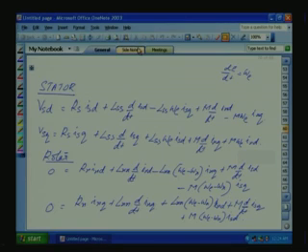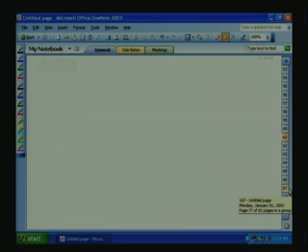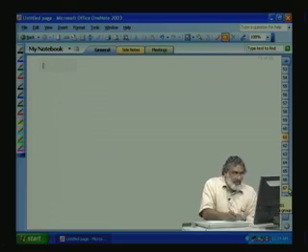Last class we derived the real and imaginary components of the stator and rotor voltage equations with respect to a general rotating dq reference frame, rotating with a speed of omega rho. If you see here, d rho by dt is equal to omega rho, measured with respect to our stationary alpha beta axis. Now, based on this equation, let us formulate our dynamic dq equivalent circuit. So, d rho by dt is omega rho, the general rotating reference frame speed. Again we will rewrite this and formulate our dynamic equivalent circuit model.